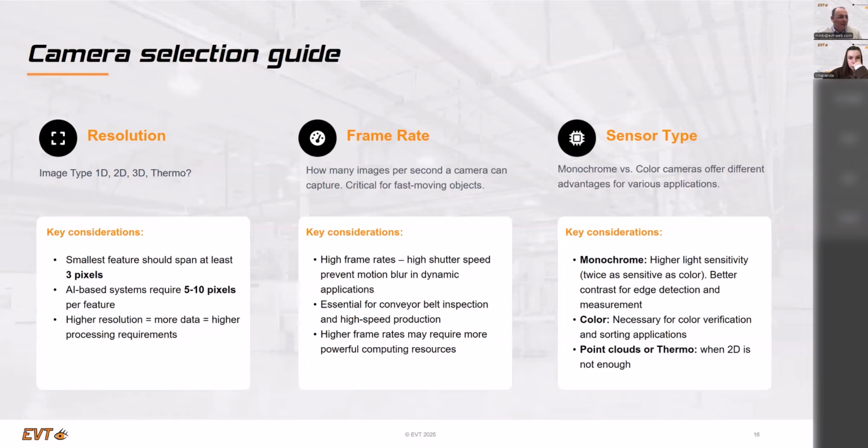If your machine can only produce 15 parts per second, of course, 200 makes also no sense. It makes sense that you save some time in the image acquisition, and therefore a high-speed camera might be a good idea, because the image transfer is very fast. If you have 200 frames, you need 1/200 second to transfer this image to your main memory, and you can use all the other time to operate on the image, but you don't need the bandwidth of the 200 frames per second, which makes it easier to connect to a PC, of course.